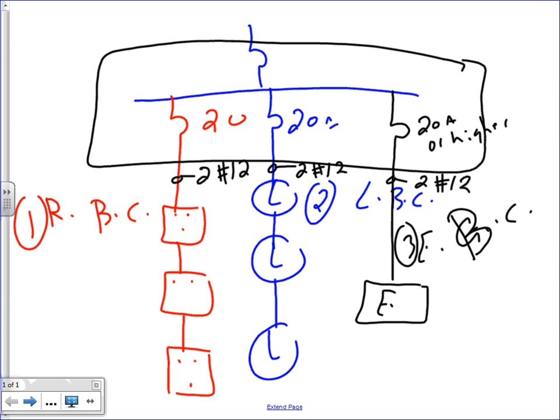So moving forward, Adam, my friend, we will not pull smaller than a 20 amp branch circuit on lighting. Can I have a thumbs up, Chad, for that one? That's what we're going to be pulling.